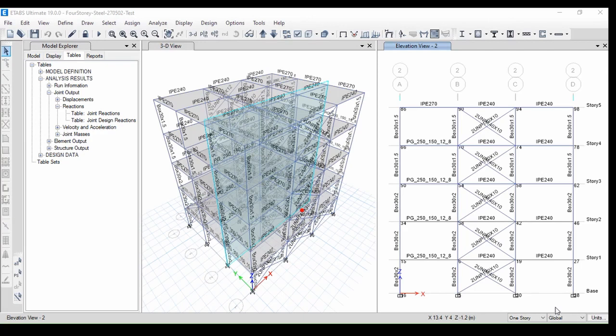Well, this is our ETABS model, a 5 steel story building. I want to design one of its base column connections. In this specific column, as you can see, a bracing element is also connected to the joint. We shall not go through designing the gusset plate required to convey the axial force of the bracing element, since it is a whole different story, but we will consider its presence on the base plate to get as real as possible. So the effect of both the column and the bracing element should be considered in the design procedure